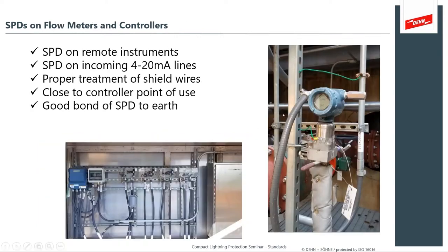SPDs on flow meters and controllers. Here we can see that the SPD is applied on the remote instrument. Check. SPD is on the incoming 4 to 20 milliamp lines inside of the control cabinet. Is there proper treatment of those shield wires? Is it installed close to the controller point of use? And is there a good bond inside that cabinet? These are the things we're looking for.